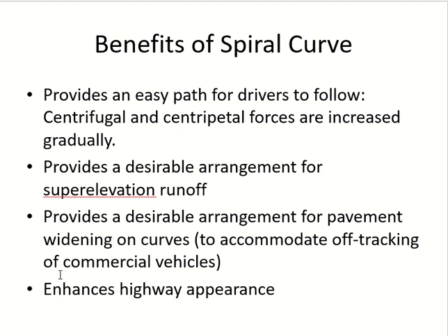So if you have two vertical curves, one with the horizontal, one without, both of them for the same speed, with the same length, everything is same, but because of the horizontal curve, this one may look bigger or smaller to the driver. So this is what they are talking about. They are the same distance, but because of the side distance, because of how it's looking to you, it can change the appearance.